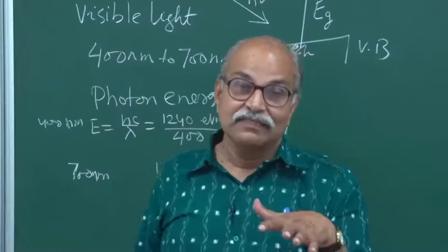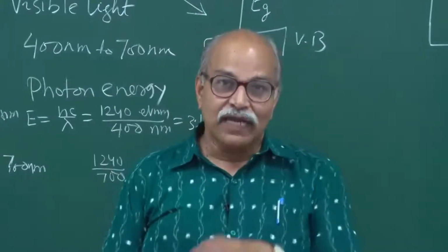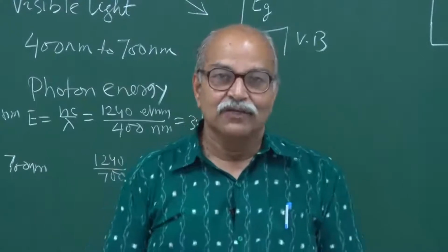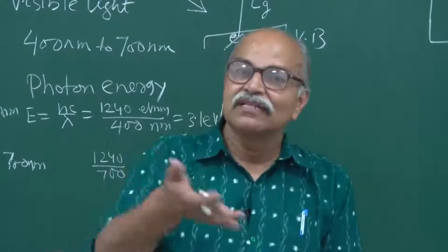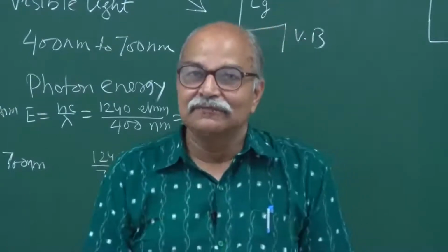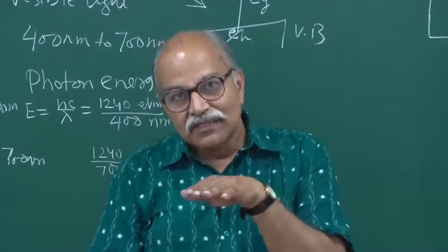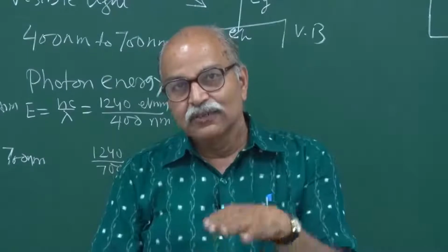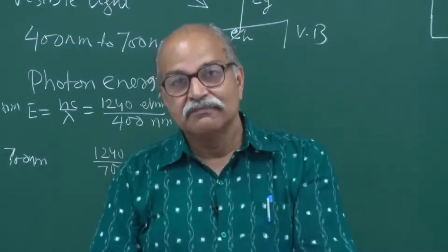So, that has to be taken care of in fabricating. The rectifying diode I showed you is all covered in blackish material, so light will not reach the depletion region. So, here it is constructed so that you have a transparent cap on this junction, so that light from outside can go and fall on this material.